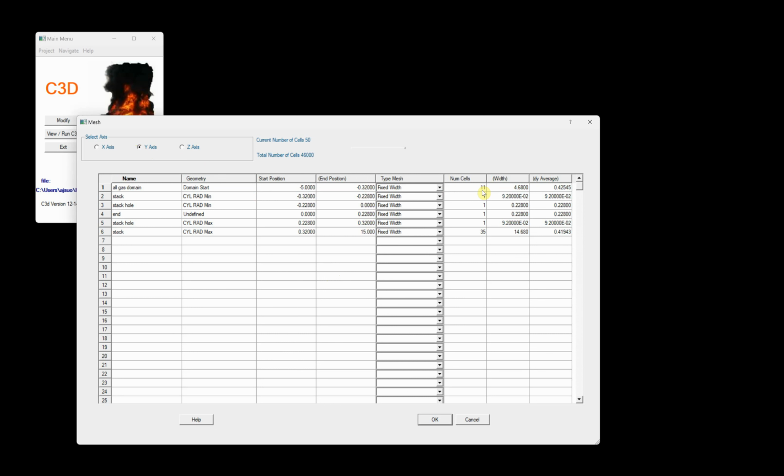We'll go to the y direction, do the same thing, delete scan mesh, give it an estimate of say 50 again. Now it's done the same thing. Here we can use 7 and a negative direction power law so that it grows in the negative direction. Here through the wall of the stack we want to have 2. Here it went from there to 0 to the center of the opening. So we'll put in 3 in order to match what we have on the x dimension so that we have square cells. And we'll put in 2 through the wall of the stack again.